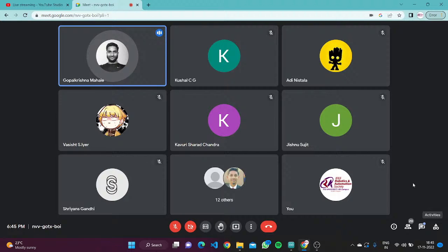When you click on that, you'll be prompted to the window which you previously edited, and you will have all the options which you selected, basically the number of teeth, the pressure angle, everything. You can change it and click OK, and all the parameters will be changed as per the selection. So basically, you need to right click on it and you'll get all the options.